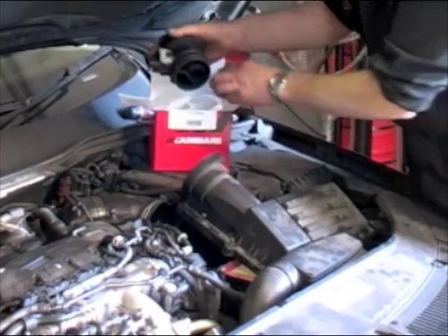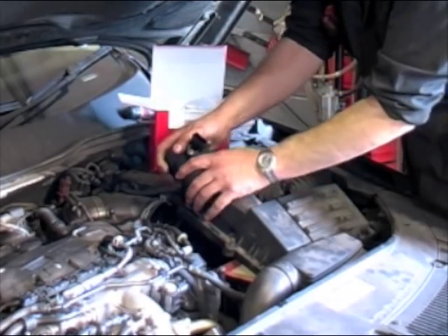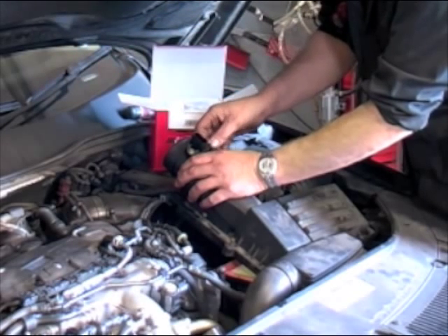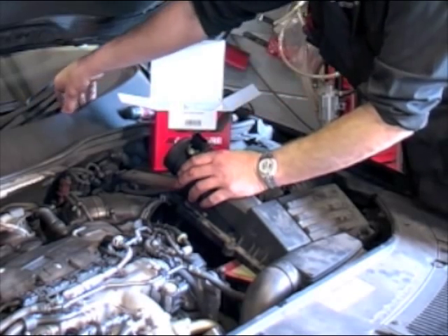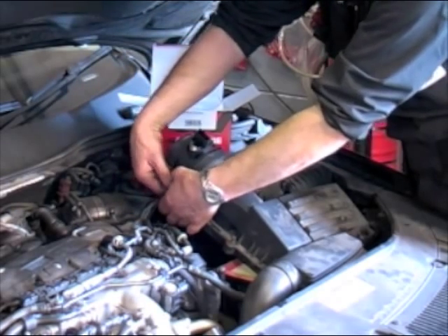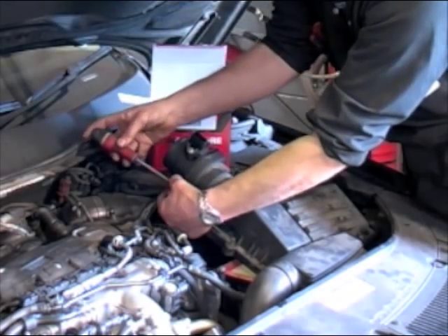It's important that the test drive should last at least 15 to 20 minutes with a variety of driving conditions through the town and faster road to enable the vehicle to complete a full cycle of sensor calibrations. The vehicle also might need to be turned on and off several times to complete this. The fault code should not reappear and the warning lamp on the dashboard should now be off.